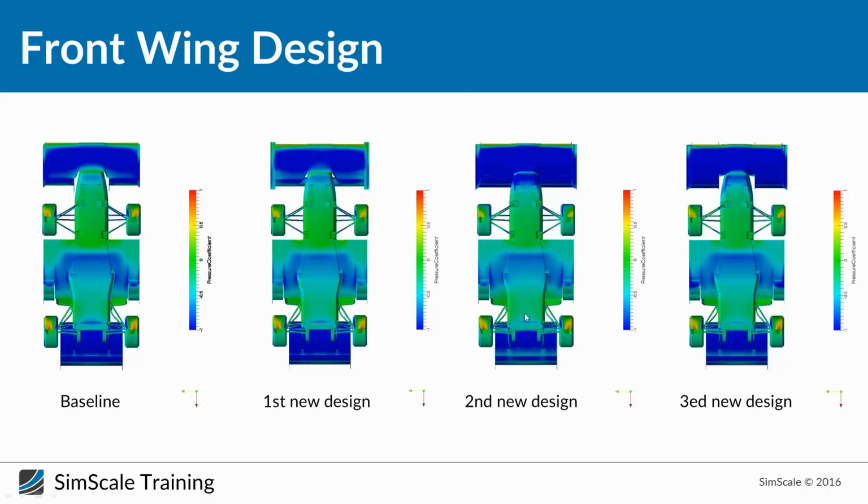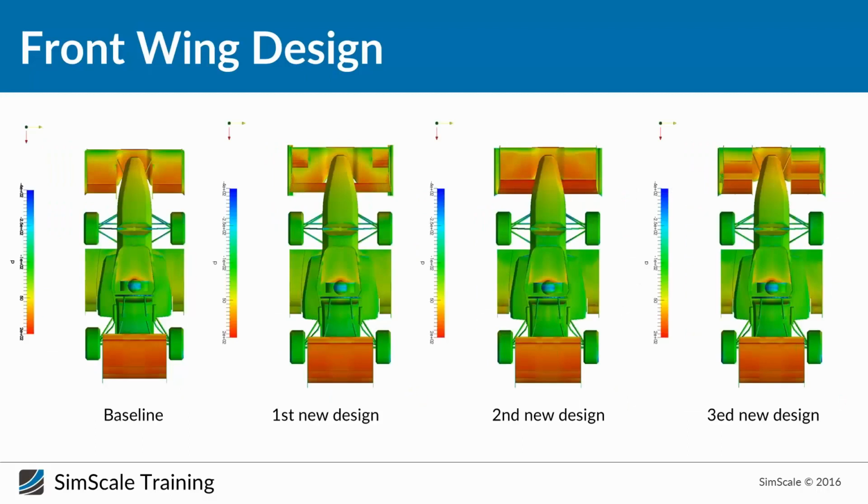So here it's like the floor of the car, and unfortunately we don't have a diffuser here. So the diffuser is just this region here. It's really small compared to the front wing and the rear wing, and probably it's because of the regulations, but that's why I think the diffuser is not really giving the same performance as in Formula 1 or in other automotive aerodynamics categories.